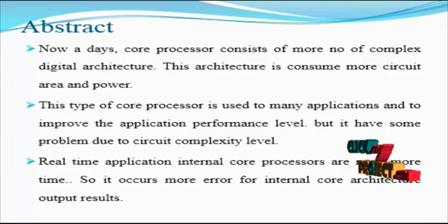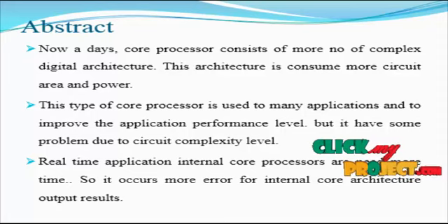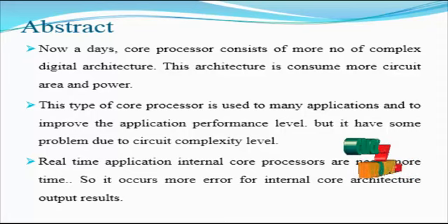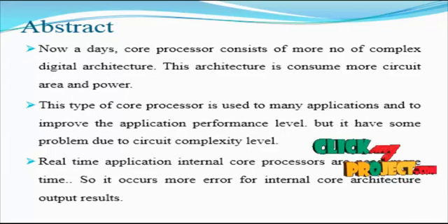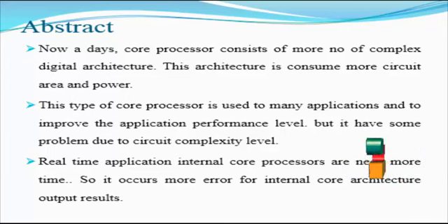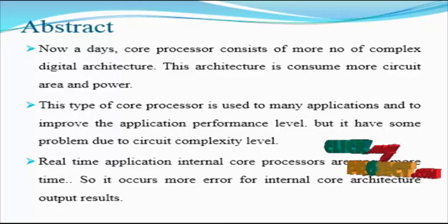Advances in CMOS technology have made digital circuits and systems very sensitive to manufacturing variations, aging and/or soft errors, and fault tolerant techniques using hardware redundancy have been extensively investigated for improving reliability. Quadded logic is an inherent redundant logic technique that corrects the errors by switching them from critical to subcritical status. However, quadded transistors cannot correct the error in the last layer, but this method detects the error and corrects it also.